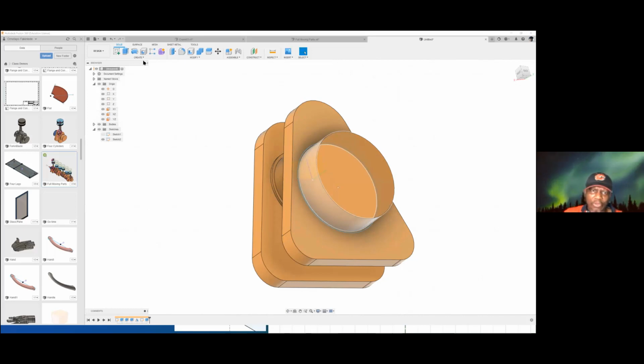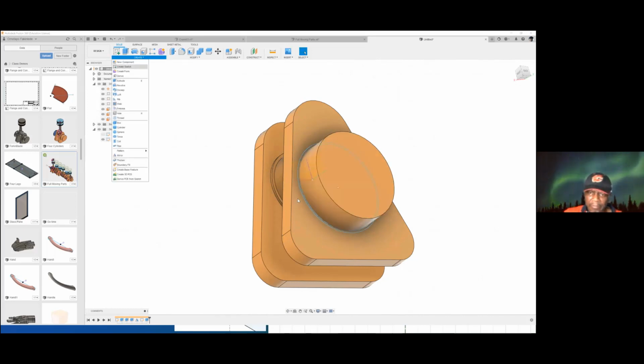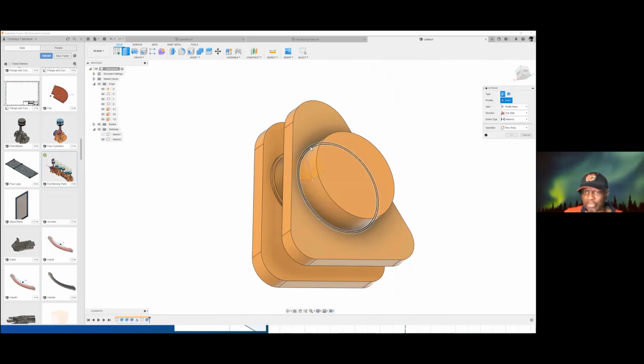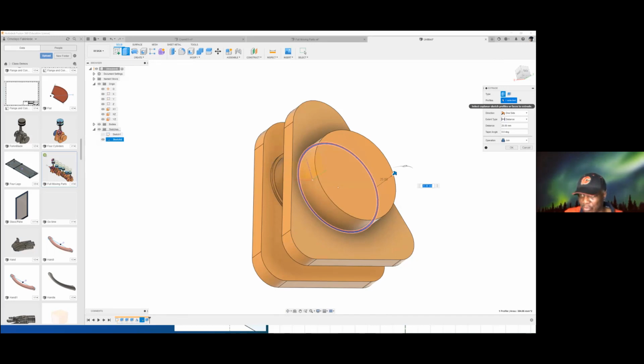So we can now do some extrusion, create extrude. Okay, that extrusion. Let us say we do an extrusion of 2 millimeters for the profile plane out. So once selected, profile plane, one side, a distance of 2, or let us say 4, because I can't see it, 4, and join it.